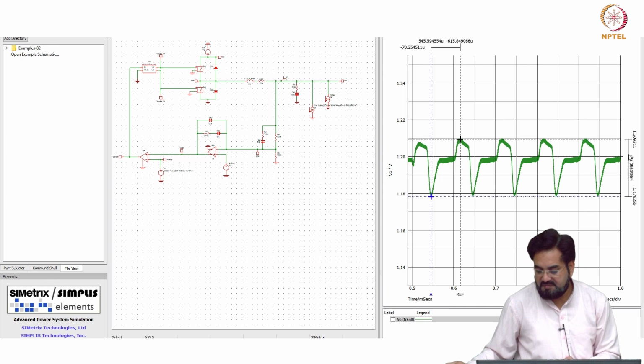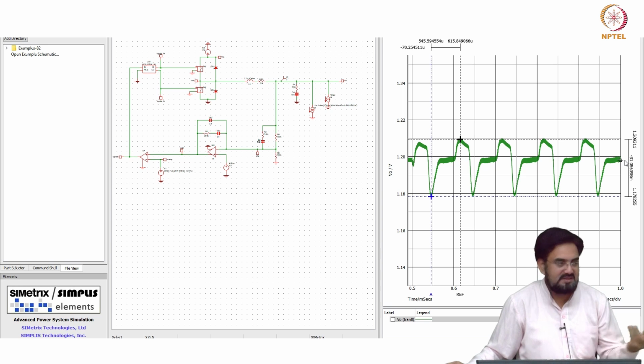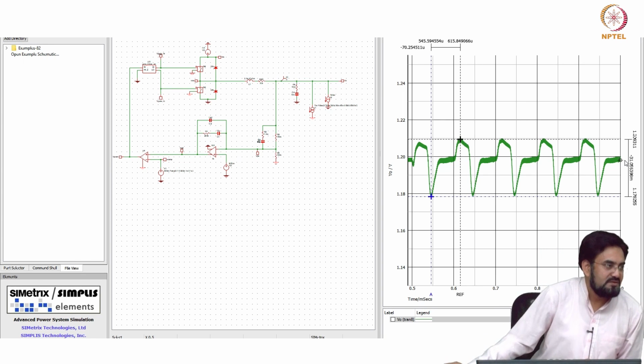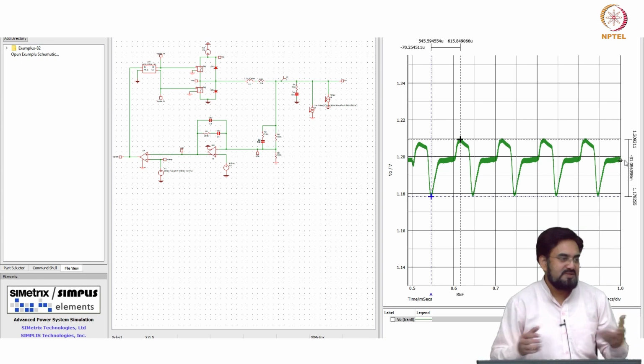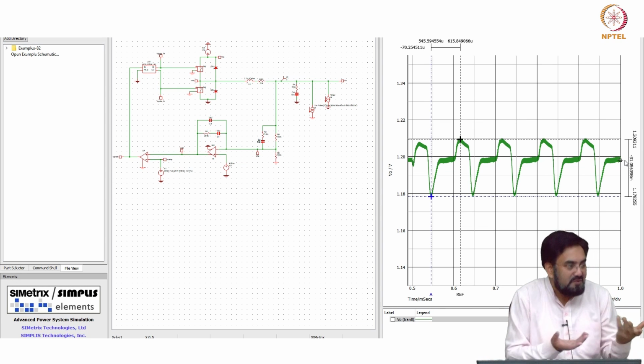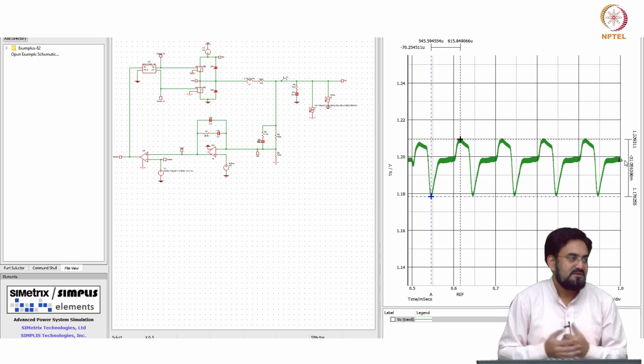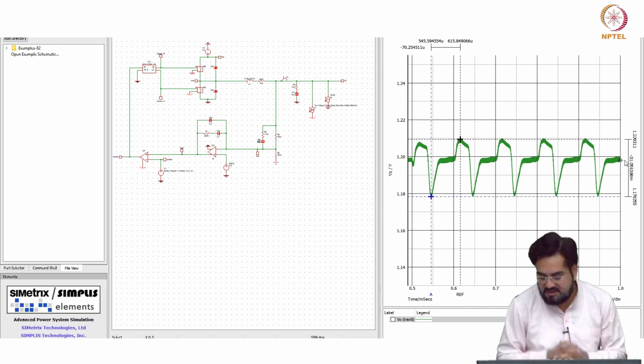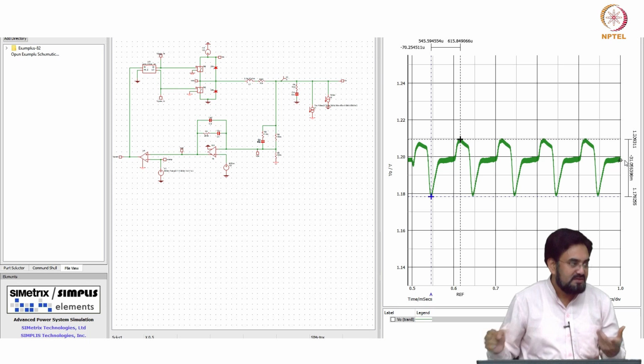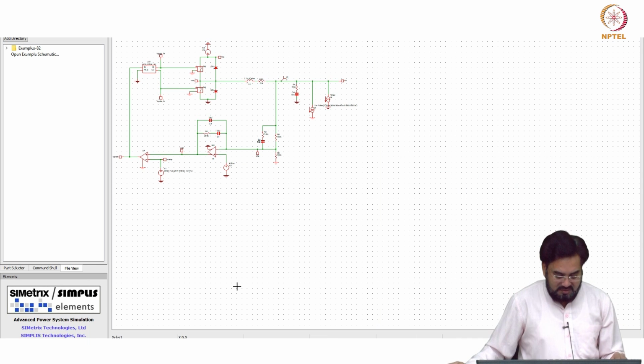We were looking at roughly 8 to 10 times if you look at the gain. After adding these poles, this may be less than 5 millivolt or so, and your ripple spec usually remains 10 millivolt or less. So as long as you have anything below that, it may not affect that much, but if you have a larger ripple, then it may affect your system. Okay.